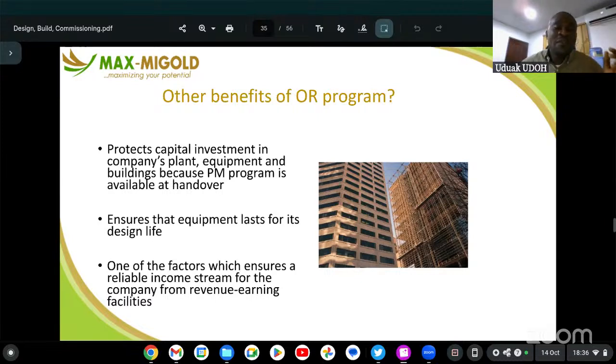There are some offices, probably the video editing office for instance, or an open space where we have multiple users. That AC will always go bad if not properly maintained, and it will always be corroded with dust. So probably every week or every 2 weeks, you try to remove the filter and wash it to avoid issues.